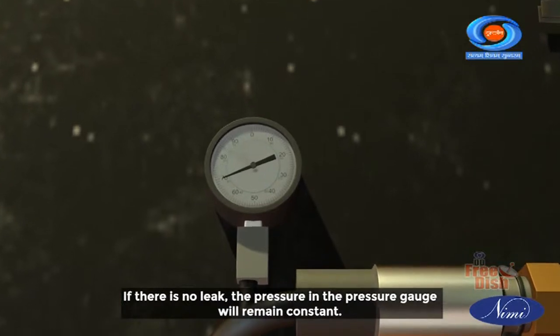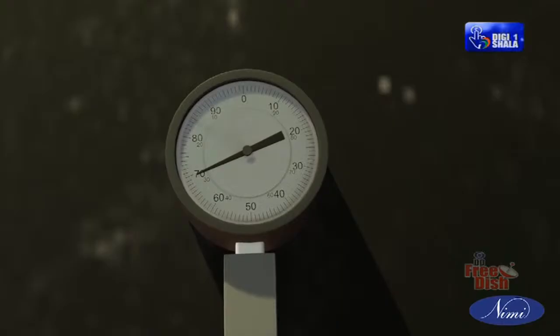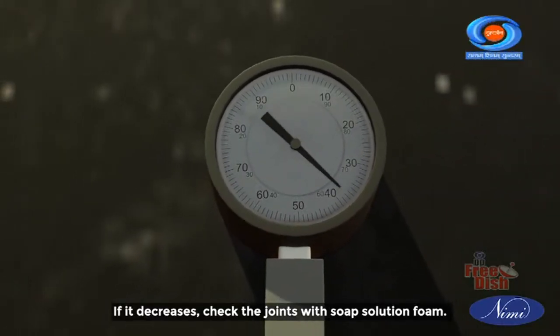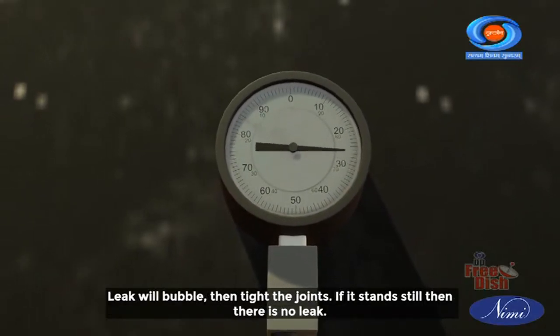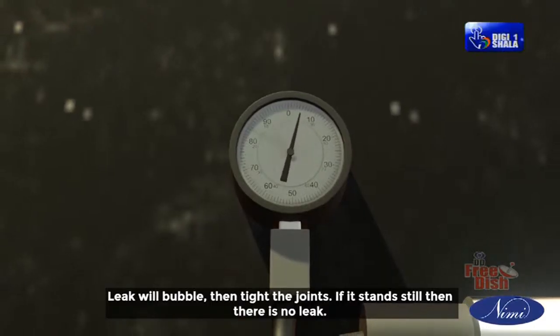If there is no leak, the pressure in the pressure gauge will remain constant. If it decreases, check the joints with soap solution foam. A leak will bubble, then tighten the joints. If it stands still, then there is no leak.